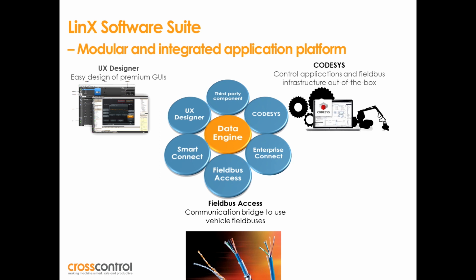But in UX Designer, where you use Qt, you can access the CAN bus for raw CAN messages, but no more. So if you want to do modern user interfaces using UX Designer, we have added the module Field Bus Access, which gives a very easy way to basically configure the CAN bus for which messages and signals that you want to access, or both read and write.